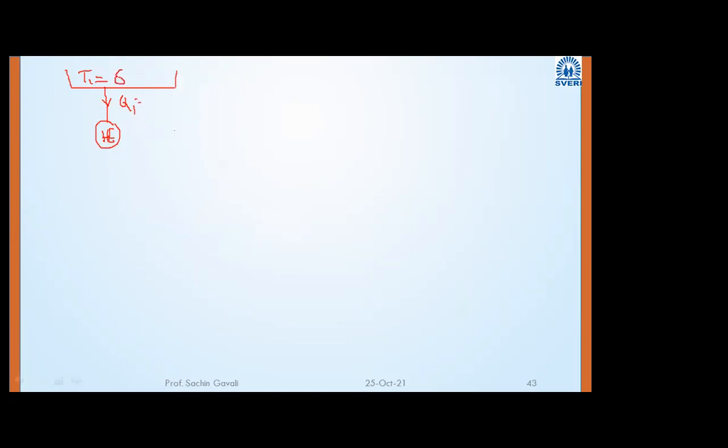Okay, 600 Kelvin. So for these Carnot cycle or reversible cycle numericals, we first have to convert all temperatures to Kelvin. 600 Kelvin, and how much are we receiving? 420 kilojoule per cycle. So per cycle means it is one cycle only. So it is 420 kilojoule. Then some amount of that heat will be converted into work, obviously, because it is a heat engine.